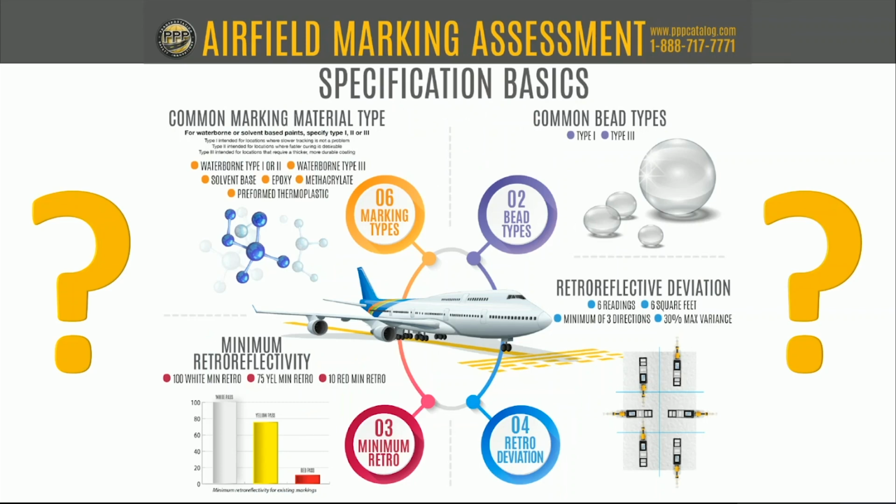The Type 3 beads were perceived to be so bright that you could not read the white inscription within that red box. So unilaterally, the FAA prohibited the use of Type 3, and they said you need to reduce the rates of Type 1 and Type 4. In my personal opinion, they have essentially created a marginally reflective marking on two very important markings, where visibility is very important, again, in low vis situations, and markings that act as a stop sign for a runway intersection.